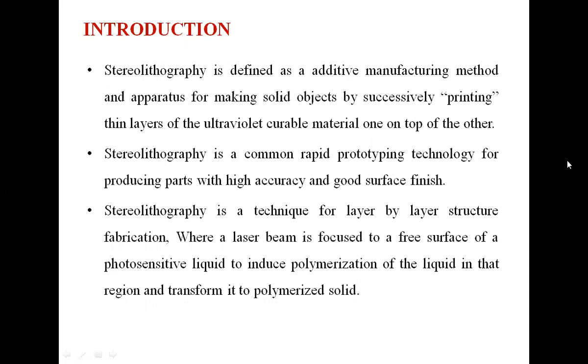It is a technique for layer-by-layer structure fabrication where a laser beam is focused on a free surface of a photosensitive liquid to induce polymerization of the liquid in that region and transform it to a polymerized solid.